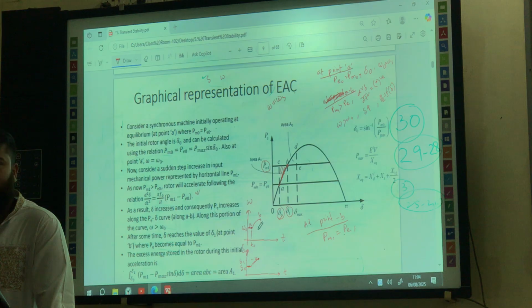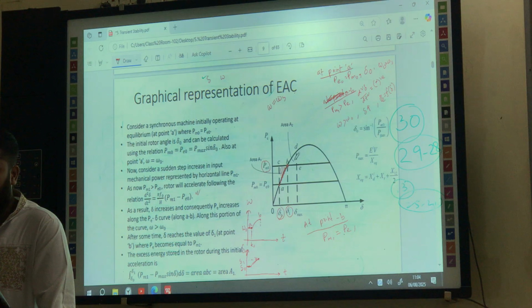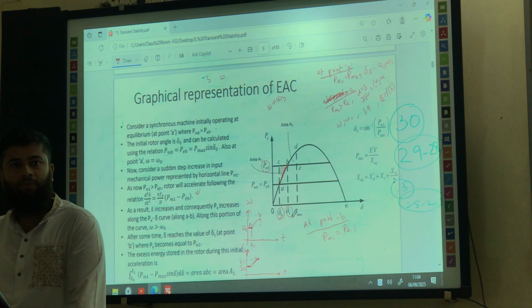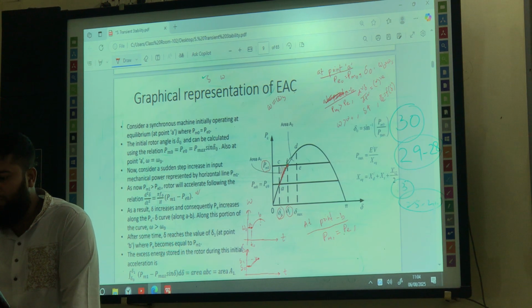No, right? Because there is some inertia, and most importantly, there is some kinetic energy stored here, right? So due to this energy and due to the inertia, this omega can't suddenly change from this higher level of omega to the synchronous speed, right? It can't happen, right? So what will it do? It actually can follow this curve. Maybe now it will come further, right? If it is the case, then also this delta will be higher.